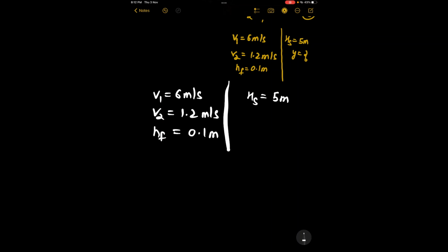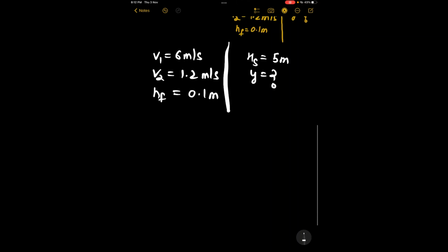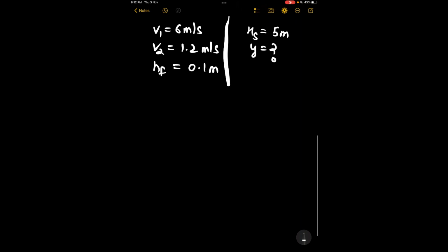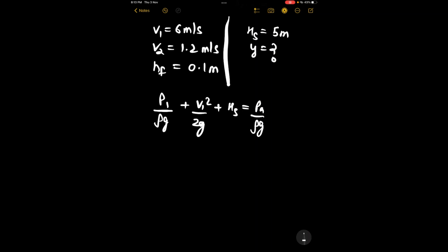We don't know the value of y over here, so y will get cancelled. Applying Bernoulli's equation, you get P1 by rho g plus v1 square by 2g plus hs equals pa by rho g plus v2 square by 2g plus hf. So y is gone.